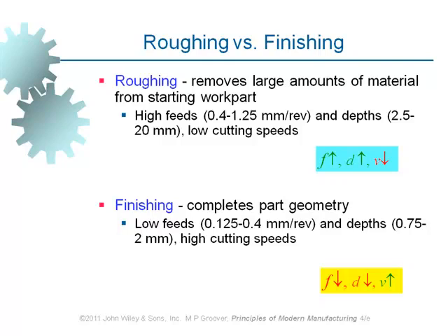It's like a digging operation which a human worker performs. Depth of cut when digging the ground. If depth of cut is really deep, and feed rate is also high, what happens? The person cannot last long, right? Because there is limited power available. The same applies to the machining operation. Depth of cut is high, feed rate is high, and there is a limit for the machining power which is made available, so cutting speed has to be low. And for finishing operations, when we are after a smooth surface finish, what gives us a smooth surface finish?